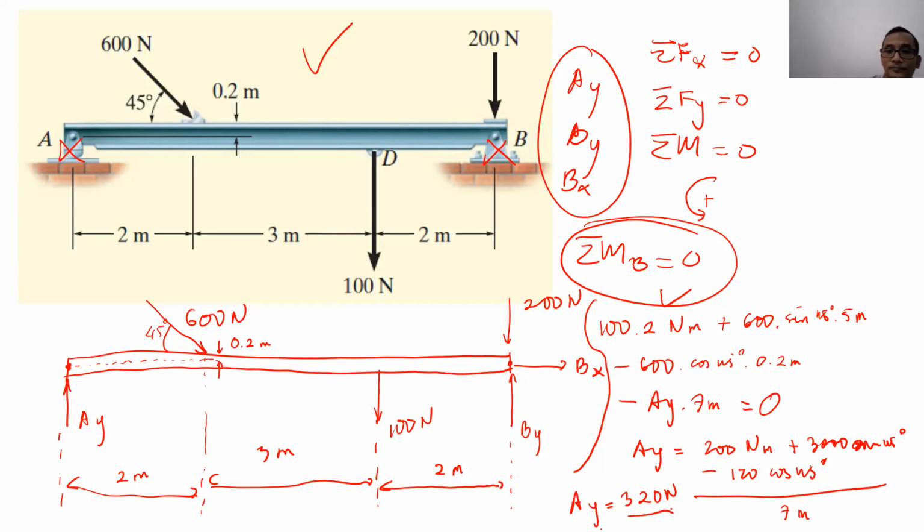Going up, right? After this, in order to solve for Bx and By, what are we supposed to do, Lilo? Just now we already used the third equation here, sigma moment equal to 0. We can use sigma Fy. Sigma Fy equal to 0 in order to find which one? Find By. By, correct. Okay, we can use sigma Fy equal to 0 in order to find By.